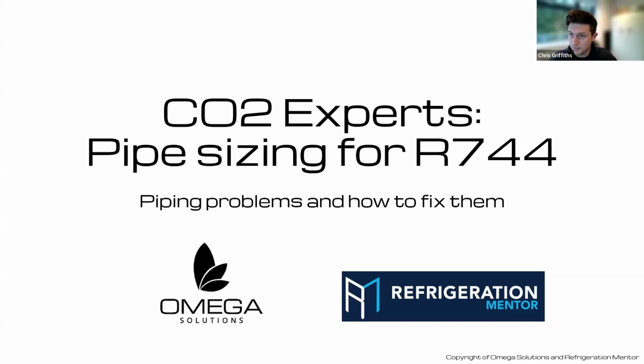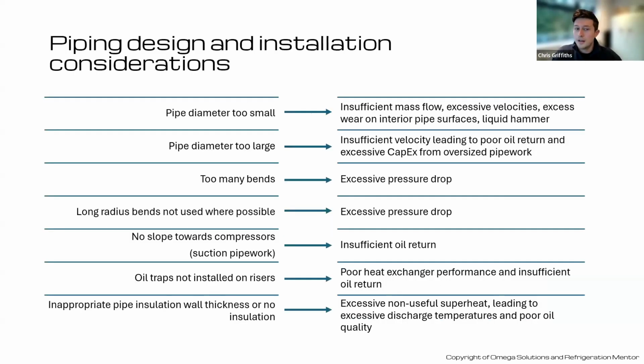So if I jump through to the next slide to start us off, hopefully this is a nice, easy reference point for everyone to refer back to if you want to. If a pipe's too small, it's not going to carry enough refrigerant. If it's too big, not only have you spent loads more money on a pipe you don't need, it's also going to suffer in terms of getting the fluid flow for your oil back to your compressors.